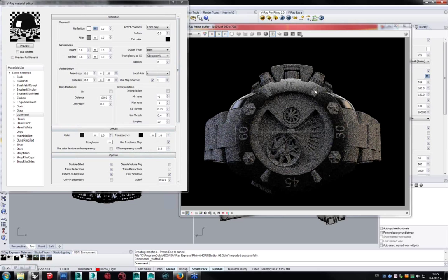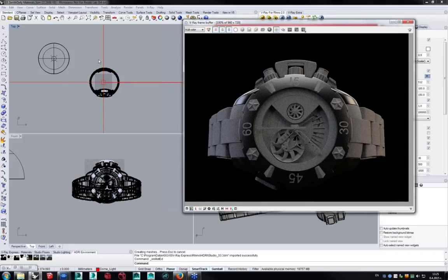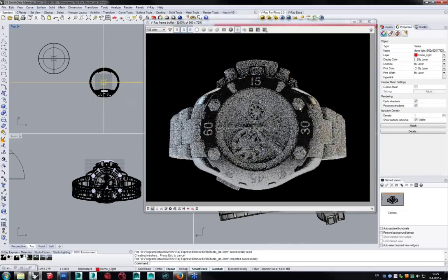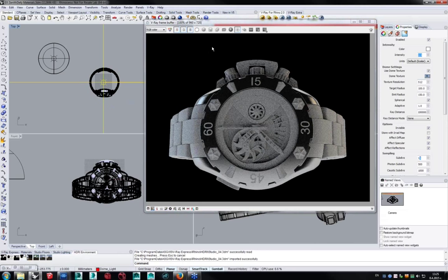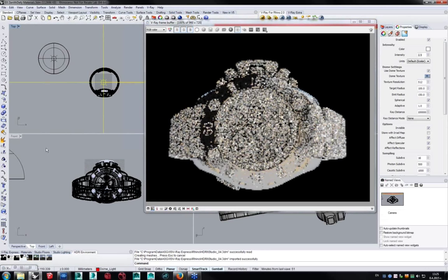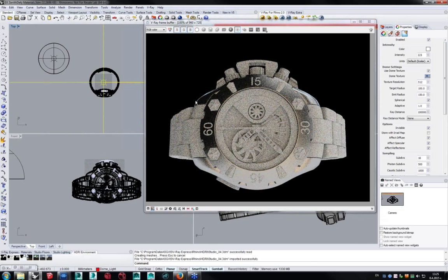But one thing that I notice is that our entire lighting is coming from very few directions, which is not good enough for me to determine whether I'm doing a proper material setup now. So what I want to do is change my lighting again. Without touching anything, the dome light, the new one from the V-Ray Express is still there, but I will add a different light setup, which is giving me light also from the bottom. So this one is maybe much more appropriate for what I'm doing. I also rotate it a little bit. There we go. So now I have a much more natural setup that I want.